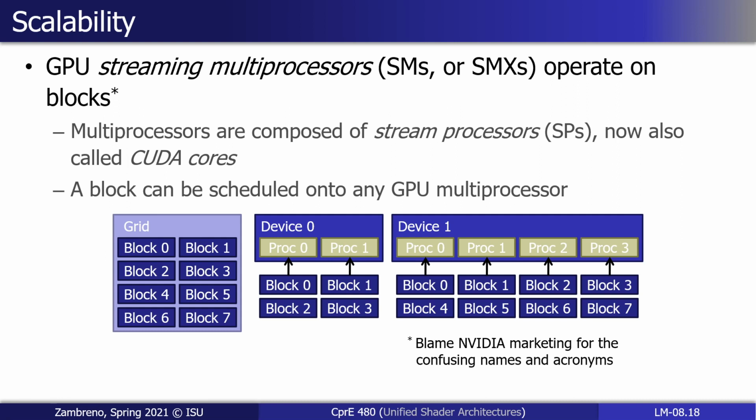Because if the resource management is such that we can execute 2 blocks at any given time on our SM, if we had 4 versus 2, we can then, in theory, execute all of those blocks at one given time. Doesn't mean that this GPU is twice as fast as this GPU. Again, the partitioning of work into threads isn't always going to be equal. And as we share resources here, we're ultimately still maybe competing for memory bandwidth and things like that. So it's not necessarily twice as fast, but in terms of thread utilization, presumably there's twice as many threads that we can execute on this GPU versus on this GPU at any given time. That doesn't exactly mean twice as much performance.